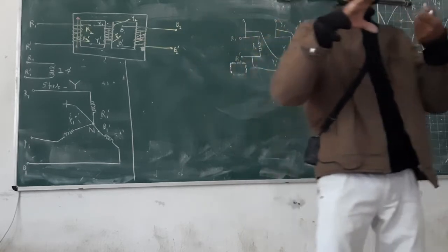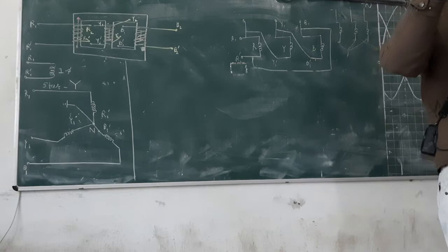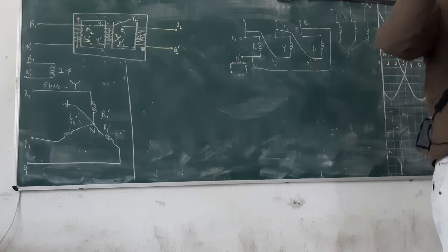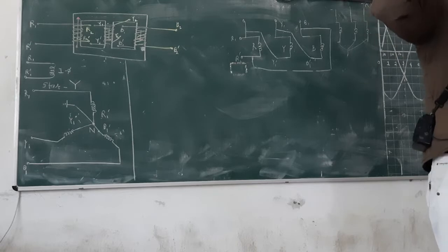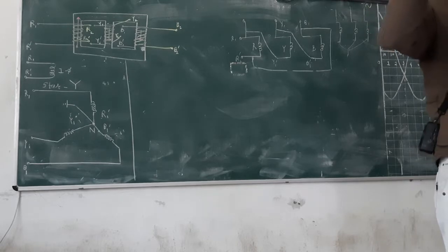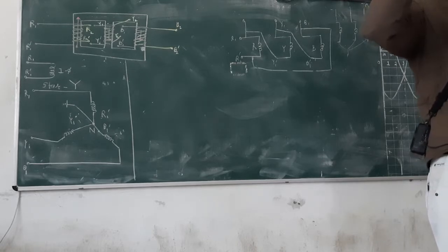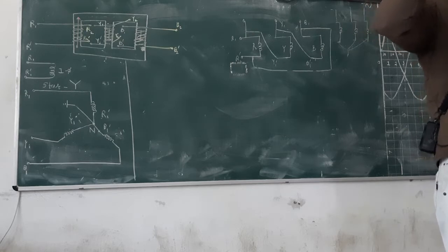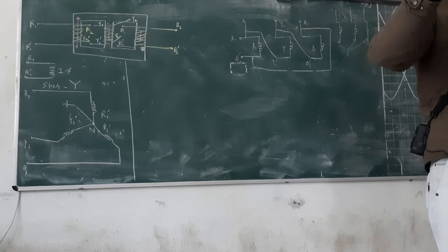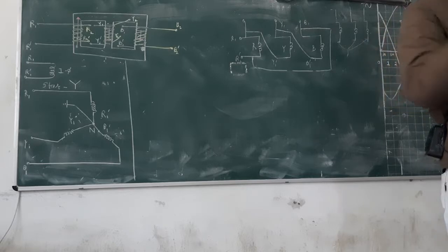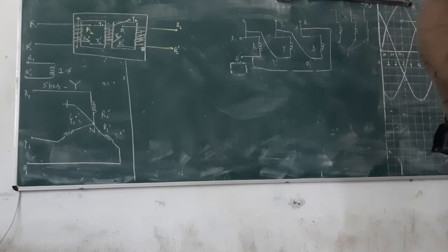If the magnetic field is not proper, then whenever the conductor goes through that pole, it will not create the maximum voltage. So 1, 2 and 3 poles are there. The generator rotates like this, the conductor goes this way and cuts the magnetic field, maximum 100 volts. Going to the next, the conductor cuts the maximum 100 volts. Going in this part, 90 volts. Some fault is there, the magnetic field is weak. So we need to treat it, we need to correct it.